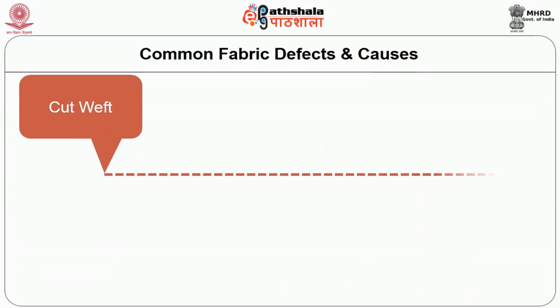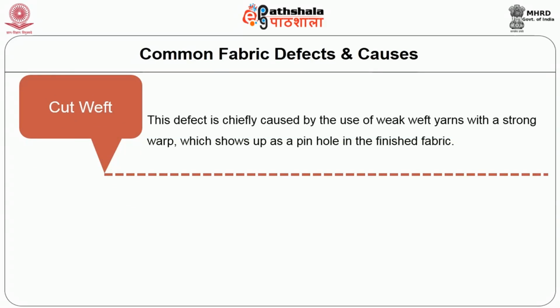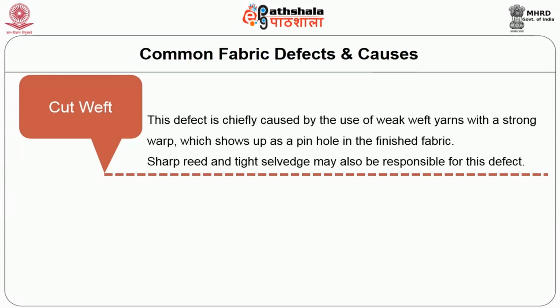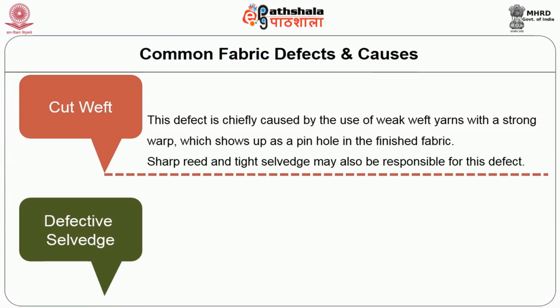Cut weft. This defect is chiefly caused by the use of weak weft yarns with a strong warp, which shows up as a pinhole in the finished fabric. Sharp reed and tight selvages may also be responsible for this defect. Next, the defective selvage.